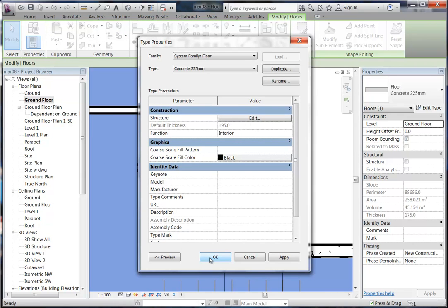If you're really fussy, and often this comes down to the way you're going to work with the contractors, you can use the slab thickness for your level. So you'd have the slab set at 0, and then the carpet would be above that. So you're always measuring the levels to the structure. But I'm not going to worry about that. I'm just going to do it to the finished floor level, which is absolutely fine. It's just another way of doing it. So, and if you're going to do that, you should put FFL on your levels.